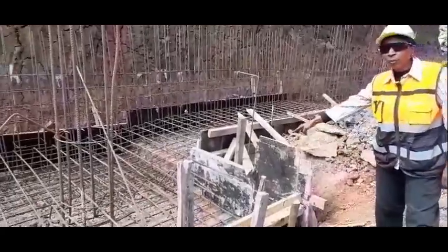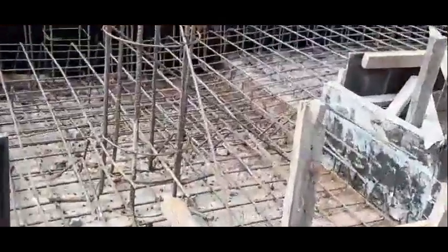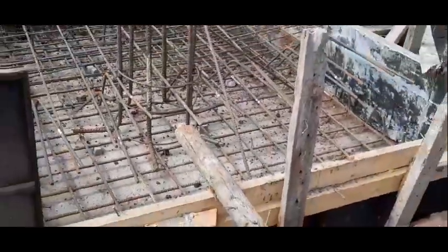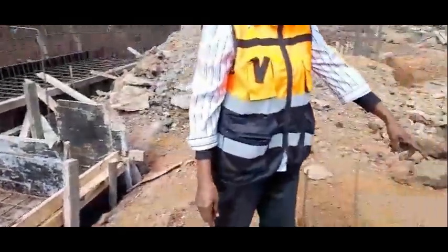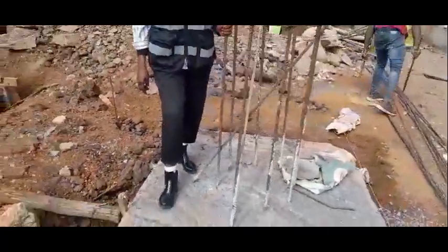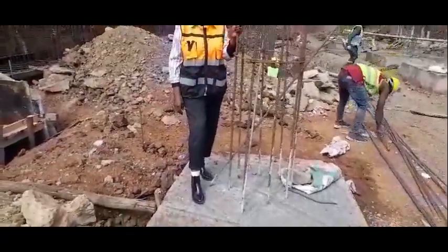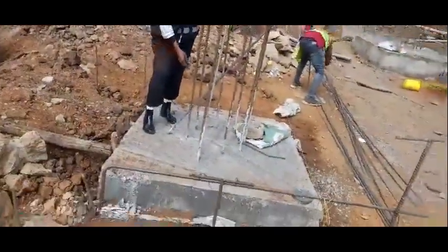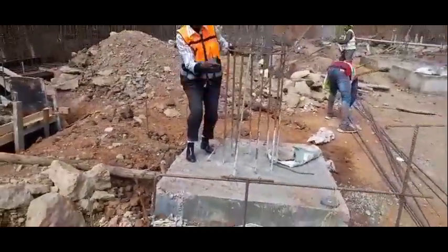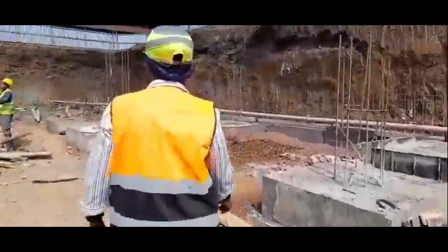And before reinforcement is placed, there is what is called blinding. Let us see, this is an example of where now the base has been concreted. I'm standing on the base which has been concreted. These are the column starter bars. And the column starter bars should be at a height, as you can see from here. Let's look at another case.